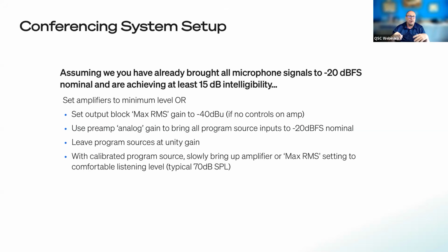And why is that number so important? Average speech, if just two people are talking and you put a dB meter out between the two of them, most human speech level, aside from my grandma, it's about 70 dB or it's about 65 dB. And so when we're in a conference call, we like to have about 3 to 5 dB more than what is normal, because it'll draw our attention to it if it's a video conference or things like that. So typically what you want to do is the nominal level of the room, when the program audio comes out of the loudspeakers, is a little bit above the normal human voice of around 65, so we set it to 70.